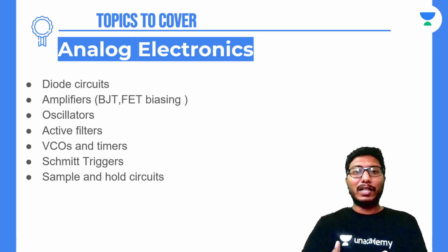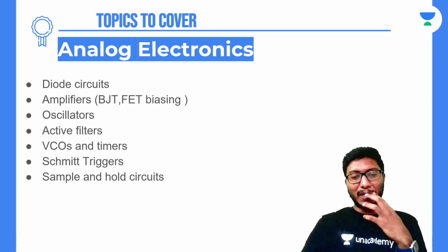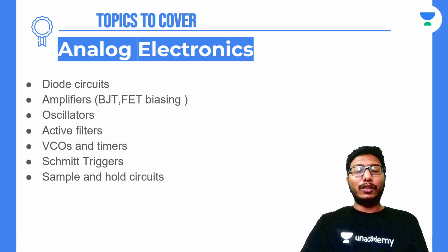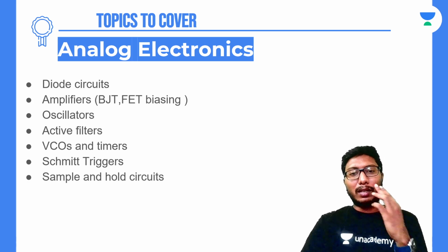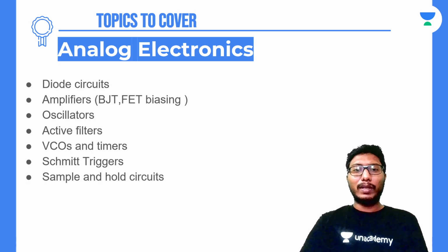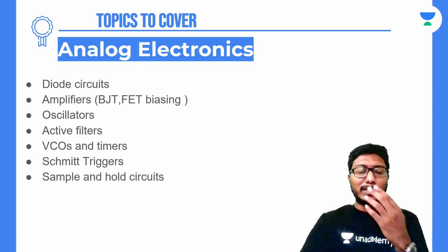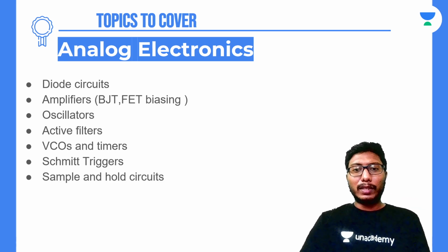So you have a Darlington pair configuration. It is not especially mentioned in the syllabus, but there are chances that you might be asked a question about finding gain, output current gain, or overall current gain for a given configuration. But you need not worry much, because it will be given with some approximations only. You need not consider everything. You will be given some approximations, but you need to know how to calculate this gain, and the method that you need to use, so that you will arrive at the current gain, whatever is asked in the examination. So mostly the current gain will be beta 1 plus beta 2 plus beta 1 beta 2. Either you can remember the formula, or you can solve the problem. That is about the Darlington pair.